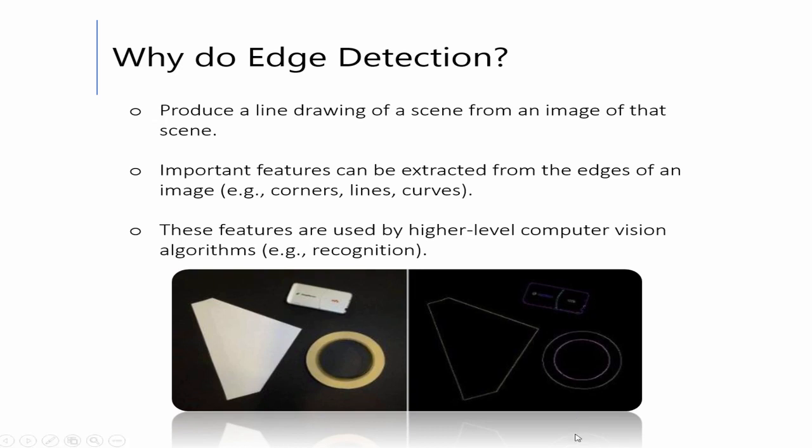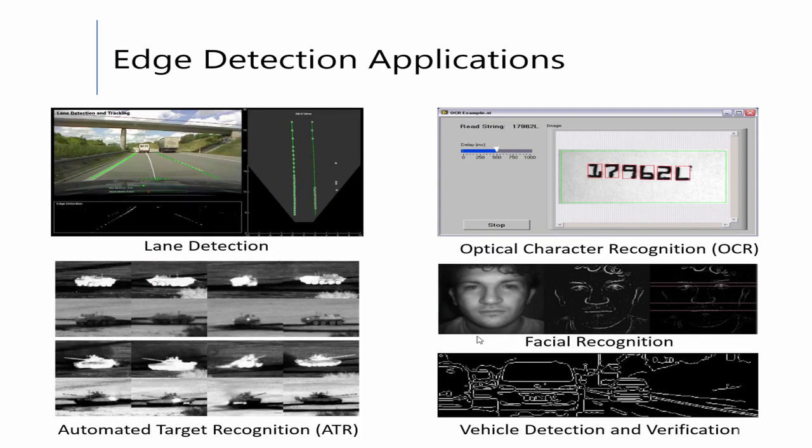If you look over here in machine vision, we want only the edge of these lines, and by using edge detection, we can calculate these coordinates and thus calculate the perimeter of this object. Or we can calculate the diameter of this circle object. And these are just some basic applications of using edge detection.